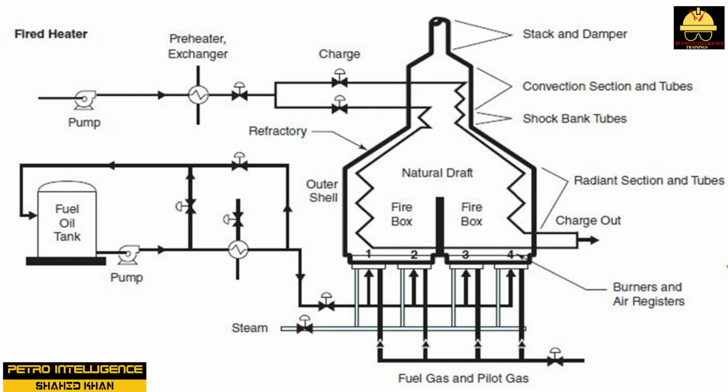Adjustments to the airflow rate are made at the burners and the stack damper. The floor of the furnace has a 6 inches layer of heat-resistant castable, capped with high-temperature firebrick. Some cabin furnaces have a bridge wall that equally divides the firebox. A split-flow tubing arrangement exits the upper convection section as product flow drops down and into the hotter radiant section.